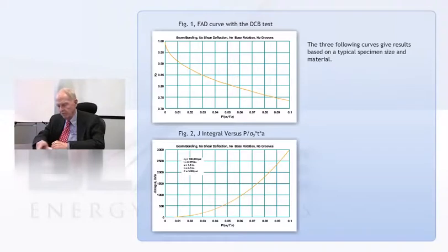There's an interesting side story that goes with that. If you've done much beam kind of analysis, particularly when you get to a short beam, you're likely to want to throw in what's called the shear deflection. So a couple of different ways to do it, but the simplest way would be to take the load in this prior problem, take the cross-section of one of the two beams, and take the load P divided by that cross-sectional area, and throw in a shear strain. Okay? If you do that using the usual beam theory, you get just nonsense when you try to go through this analysis that I just went through.